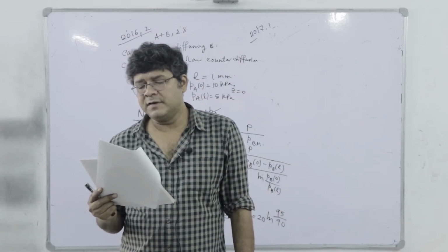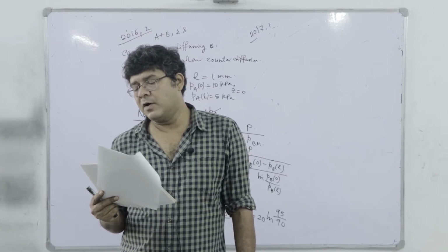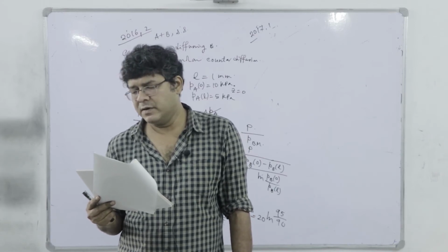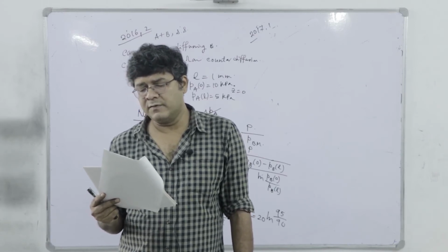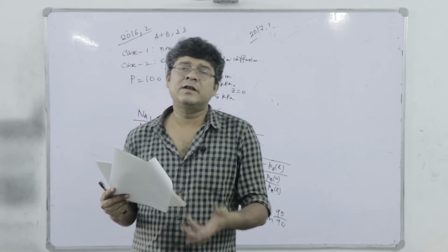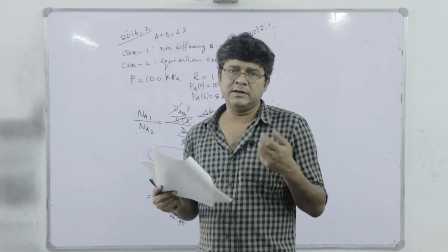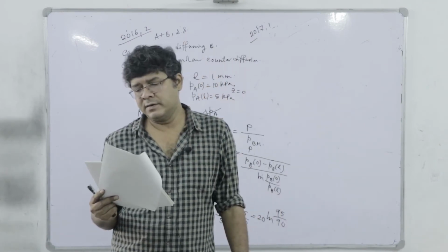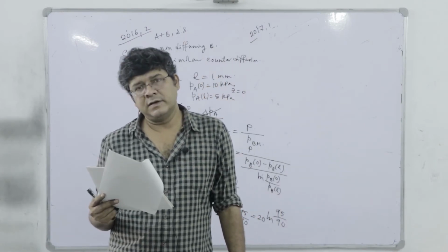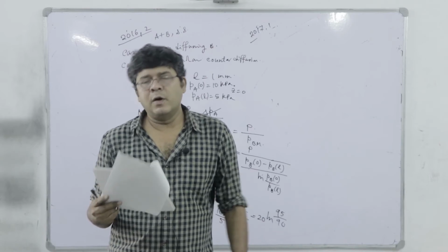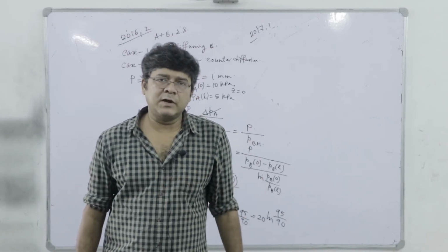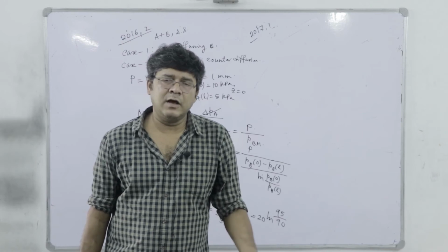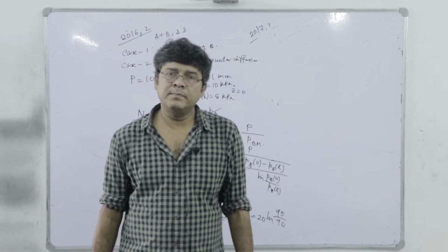The absorption of CO2 from a reformer gas, CO2 and hydrogen, into an aqueous solution of diethanolamine. So, this diethanolamine, ethanolamine, etc., they are very good solvents for carbon dioxide, right. So, once it is a very good solvent for carbon dioxide, my Henry's law coefficient M will be low, right.